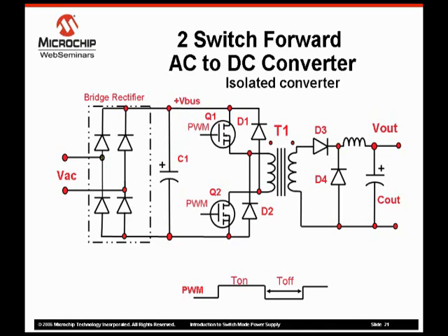There is one power pulse transfer of energy per PWM cycle. This requires a larger output inductance and capacitance. The core utilization is not optimal since the flux excursions are in the first quadrant of the hysteresis loop. The input to output voltage transfer function is simple and straightforward.